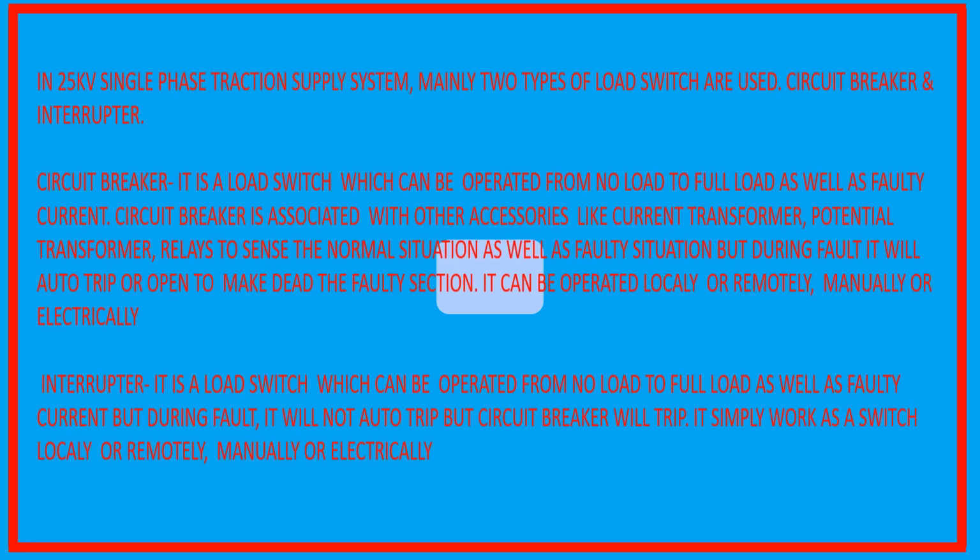In a 25 kV single phase traction supply system, mainly two types of load switch are used: circuit breaker and interrupter. Circuit breaker. It is a load switch which can be operated from no load to full load as well as faulty current.